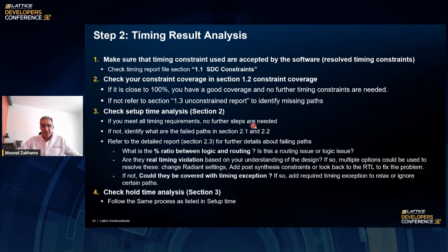And if you meet all the timing, no further steps are needed. You're good to go. You should be fine. If not, and I define some timing paths that fail the setup check or the hold check, then these will be listed in sections 2.1 and 2.2. You can refer to the details of all these paths in section 2.3.